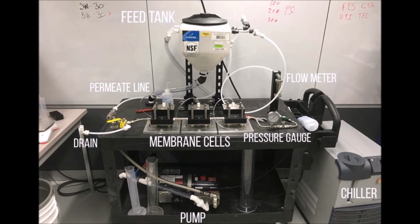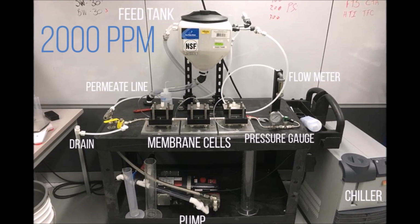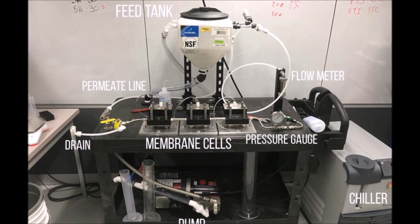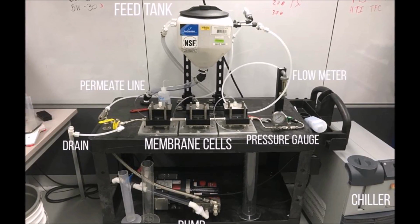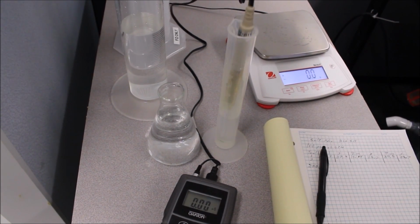Then mix a concentrated 1 liter sodium chloride solution to bring the feed tank to 2,000 parts per million of salt water. Take a sample every 10 to 15 minutes from the permeate lines over the course of 1 hour. Record the flow rate and conductivity.